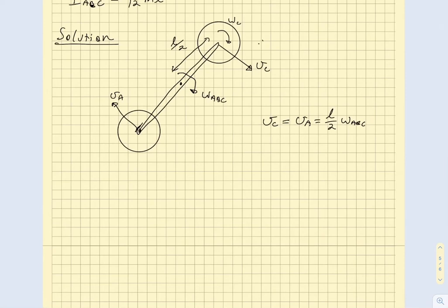And if we look at this part here, this should also be rotating omega C. Since we're almost looking at a specific point, if we picked any point in position, we can relate the omega C to the velocity C by saying that omega C should just be equal to my velocity C over r.